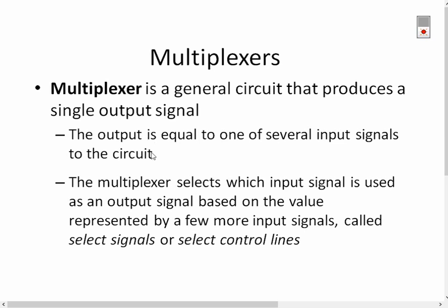And in this particular circuit, and you'll find that this is extremely valuable, what happens in a multiplexer is that I may have multiple inputs coming in and I have one going out, where I select from the available inputs to send the signal out. And a demultiplexer is where I have one signal coming in and multiple ones coming out. And the way that I select which one is going to be selected as the appropriate input or as the appropriate output, depending on whether we're doing this with a multiplexer or a demultiplexer, is with a series of what we refer to as select bits.